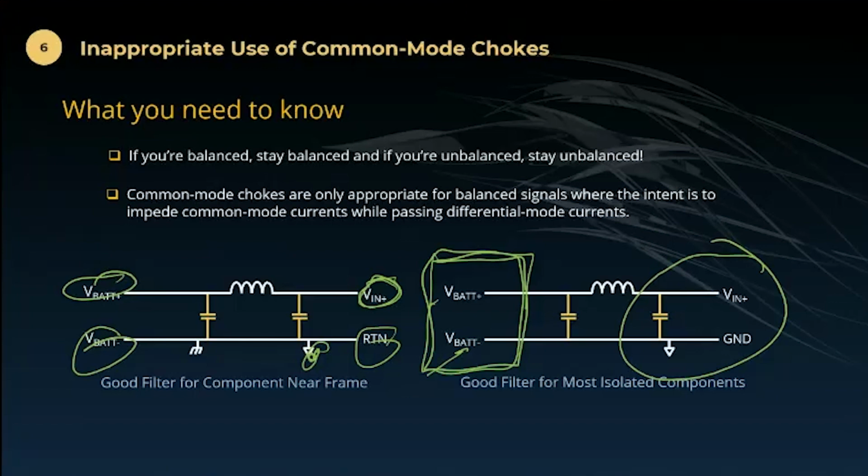It was basically, if we call that common mode, well, we can call it differential mode or common mode. It doesn't matter. There's only one mode. The thing to do is filter it, and then it doesn't matter that you converted here. If we say we were unbalanced here and balanced here, what we're going to measure here is going to be half common mode and half differential mode. That's fine. If we filtered it here, we've taken care of the problem. We don't have to worry about mode conversion. Don't be thinking, I need a common mode choke because I have both common mode and differential mode. The common mode was created by the shift from being unbalanced to balanced.